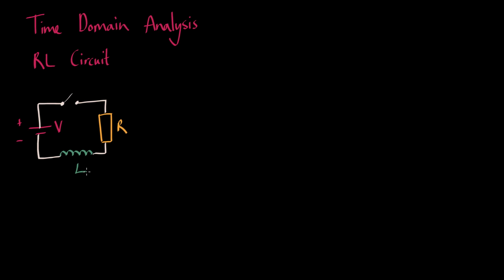Note, this circuit has a DC source, meaning there is no frequency component. While it is a fixed voltage, note that initially there is no voltage drop over either component. The voltages over the resistor and inductor will only change when the switch is closed at time 0.